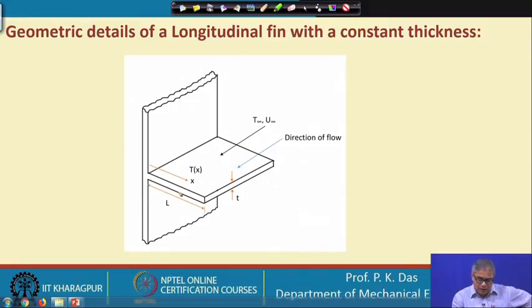Another thing, if we assume that the fin is very large, the fin is very large along this direction and along this direction. So, one need not consider a temperature variation along this direction. I have told that this fin is very long in this direction compared to its thickness. So, along this direction there will be temperature variation, but along this direction there will not be any temperature variation.